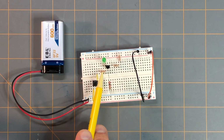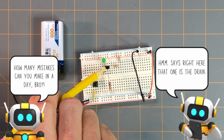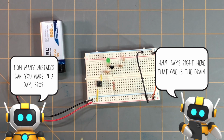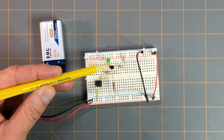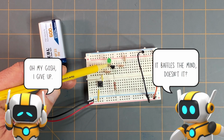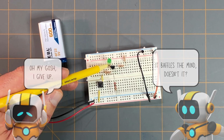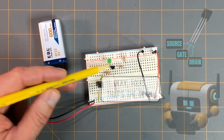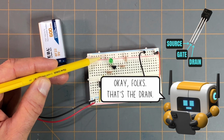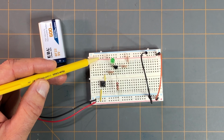Looking back at the MOSFET, its source pin is this left pin from your view above here. I know you can't see the pins, but it's on the left side as the MOSFET is currently oriented. And that source pin is in line with the cathode of the LED. And then the anode lead of the LED goes to the positive power rail on this side of the breadboard.